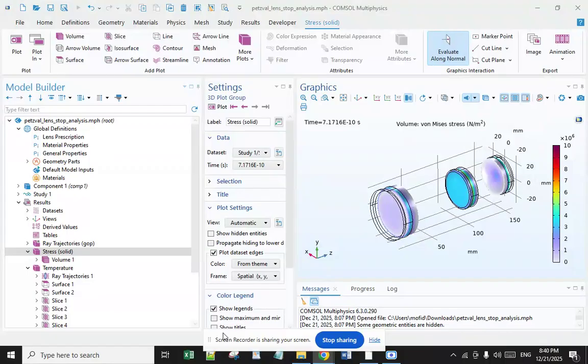Ultimately, the thermal analysis step allows us to account for the material composition and structural design of the satellite and its optical payload. The goal here is to calculate the thermal load on the payload, with particular attention to periods of peak load. Time instances with either the max or mean temperature or the strongest thermal gradients will likely be when the most significant structural deformations happen.